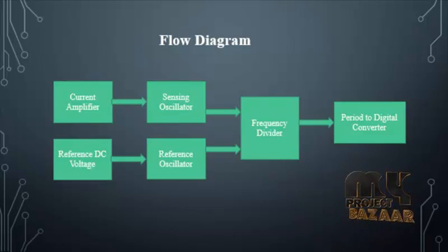The output of the capacitive micro-machined ultrasonic transducer is directly applied into the current amplifier. The current amplifier is utilized and integrated with the CMOS cells to minimize the parasitic capacitance and enhance the sensitivity of the overall ultrasonic system. The current amplifier has two PMOS and two NMOS devices. It amplifies the output of the capacitive micro-machined ultrasonic transducer using clock pulse.